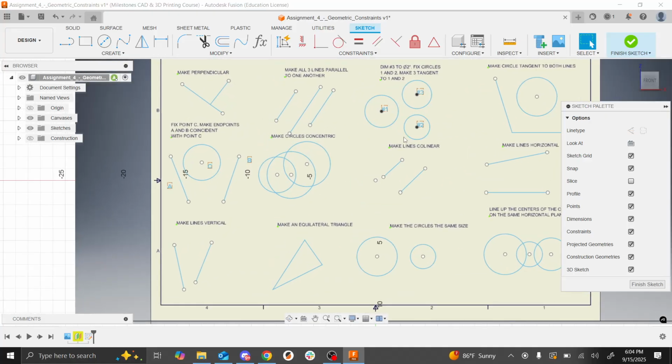Yeah, if you open up the side panel, okay, I'll just do this for everyone. So if you accidentally made a constraint that you didn't want to make, and then you made a bunch more later, and you decide that you want to delete it, you can hold Control Z until it disappears, which is probably not ideal. Or you can show or hide the constraints.